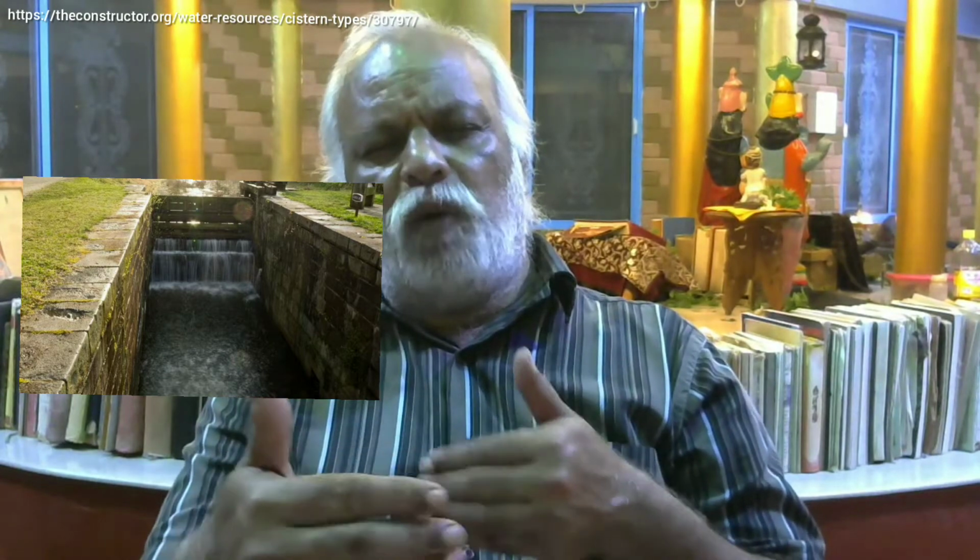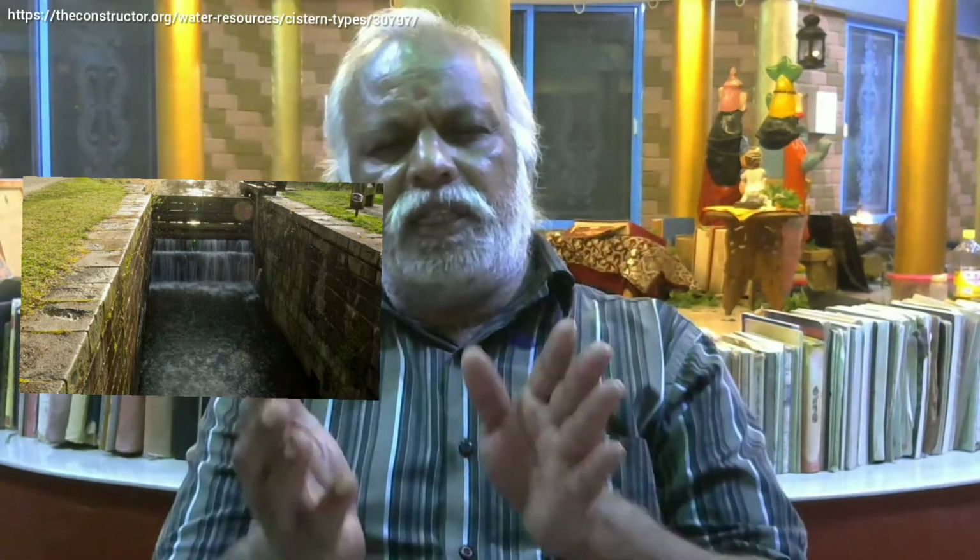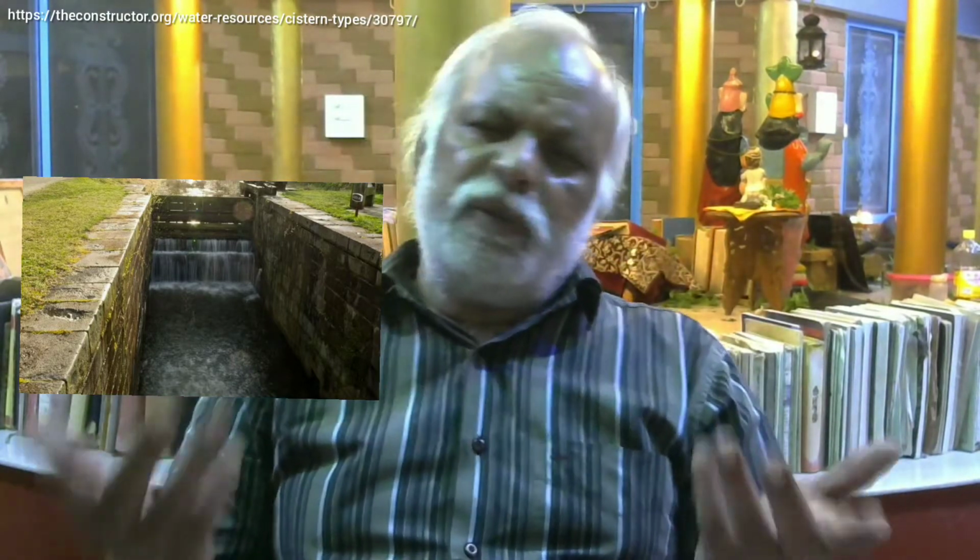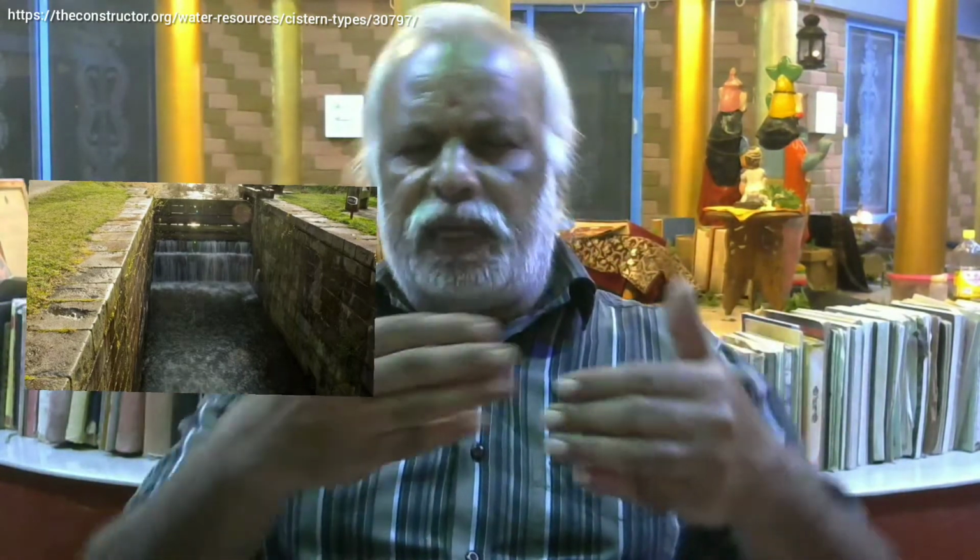It will have a body wall, then a notch. To hold the notch, you will have the notch pier. Everything will be made of masonry. And to facilitate smooth transition, the sides of the notches will be curved. So there will not be eddies. Eddies are nothing but back current, flow getting reversed. So to avoid that, you will have a very smooth, curvilinear transition. So water goes very smoothly to the downstream side.